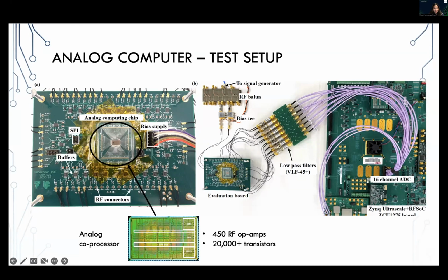I also wanted to show you this figure because this is the bare die and these tiny wires. This is the chip when you look at it under a microscope. If you take a microcontroller, you will see that the chip is a black package, and this is what you see inside that black package. There's a bare die, and it has several pads, and these tiny wires can be aluminum or gold wires. They are connected to the PCB. This process is called wire bonding. Even in an Atmega microcontroller, inside that black package there's a chip wire bonded onto the package.